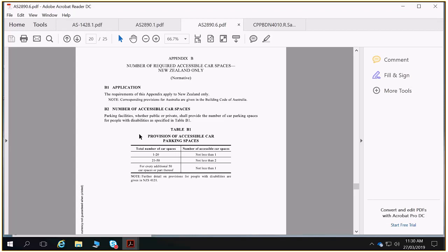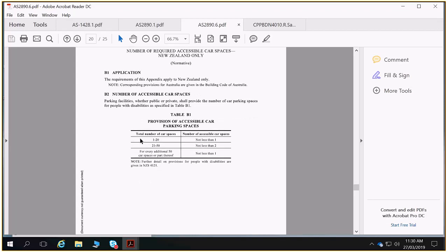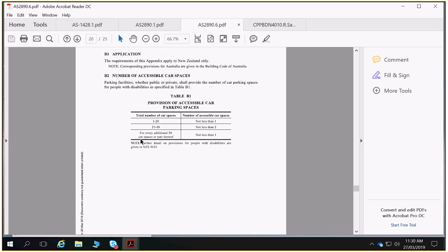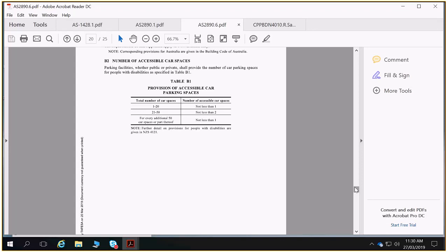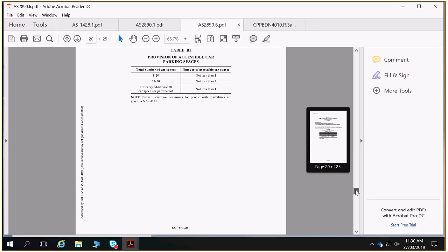So hatching for the shared area, but you also have to show that wheelchair symbol. That one's there as well. So that will be drawn complying. So we don't need to go through the size and shape of that. So you have to put in those indicators and the bollard to restrict movement as well. So drop in the bollard, drop in the hatching and the wheelchair symbol to define that as disabled car parking.